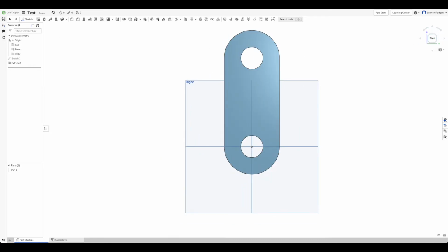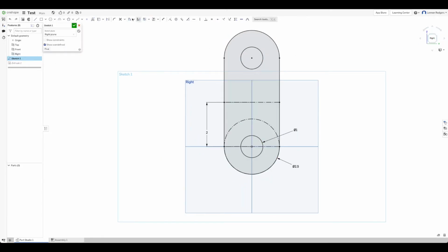You can do this inside sketches. So I can go back inside the sketch. I'll show you how to make, for example, a circular pattern. You can do linear patterns, you can do all kinds of things. So I'll just show you what I mean. Let's say you want a circle here, and you want to create some type of pattern of circles all around this center point. So I can specify that first circle, and again it's blue until I add a dimension. I'm going to add 0.25, and then I need to specify its location. So I'll say 0.5 inches.